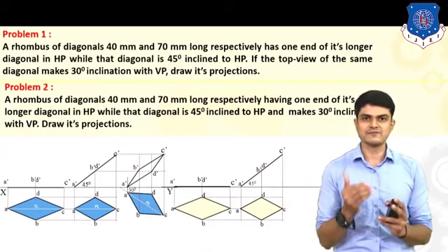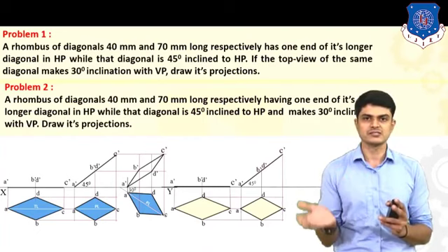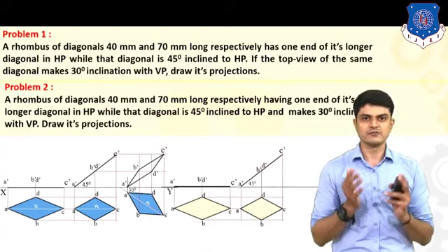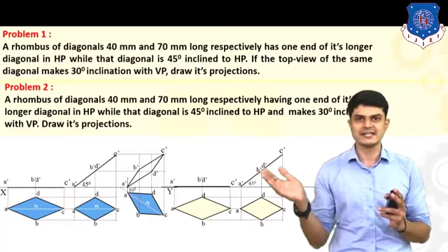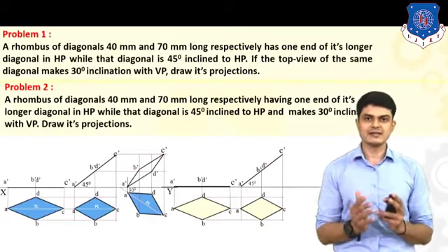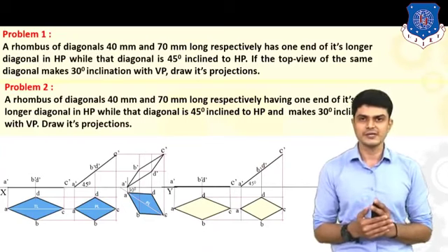After giving numbering, let us find out the front view in VP. So let us draw vertical lines from each and every point. So we will be having a horizontal line on our XY, which is nothing but your A dash, B dash, D dash and C dash. After that, let us find out the second stage drawing.